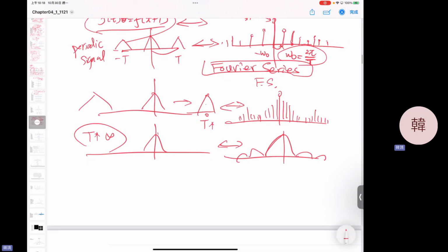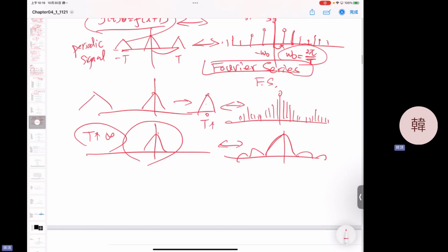So what's the next step? This is the time domain. All the signals you hear and watch are continuous time, continuous space coordinate images. However, if you want to process it, you have to digitize it. You have to sample your signal, right? So how do you sample it? We taught you an impulse train, a comb function. You are going to sample your signal.